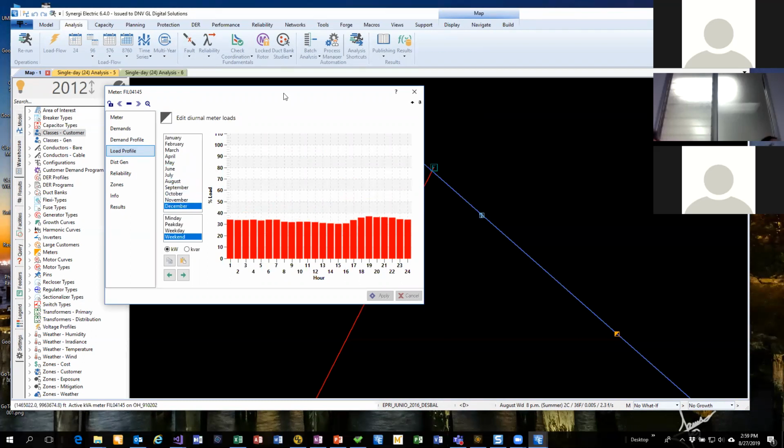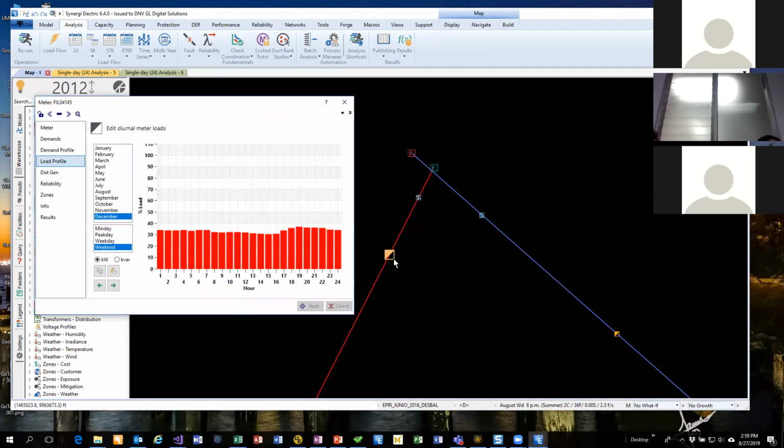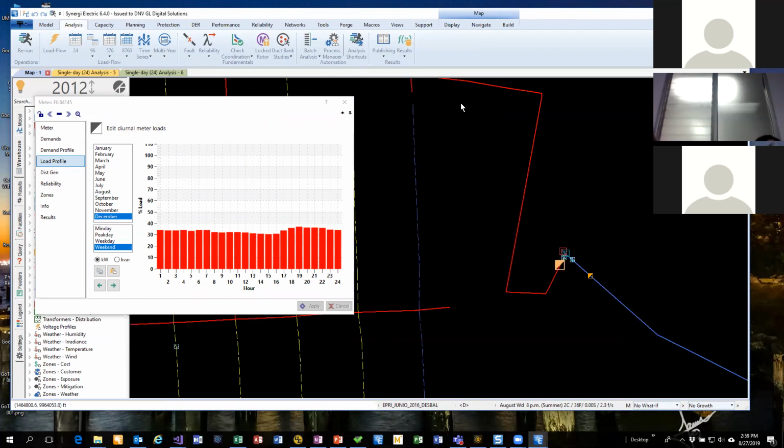So it's very good. This is the actual demand on the meters. We're using it to represent the load behavior of all the loads on the model. Now that's an engineering estimation, because there's probably no single load in this feeder that is doing this exact thing. But all of the loads together are doing something very much like this. So it's a good engineering approximation. The great thing is that the data is available, and you saw how easy it is to bring the data into Synergi.